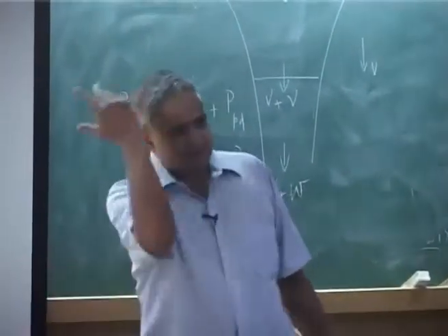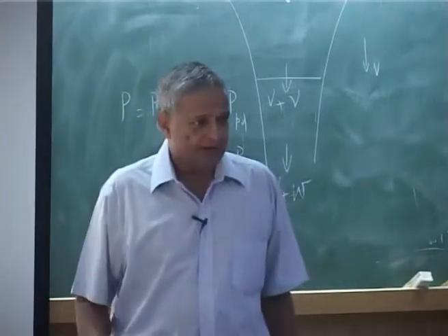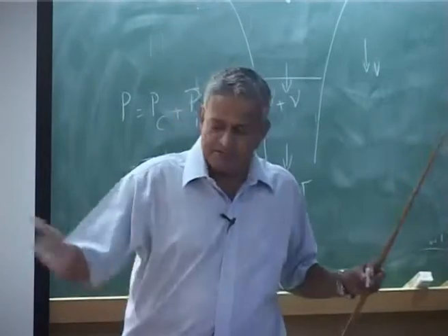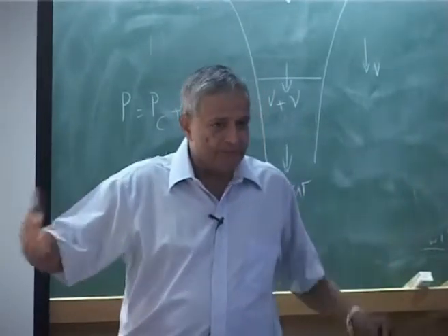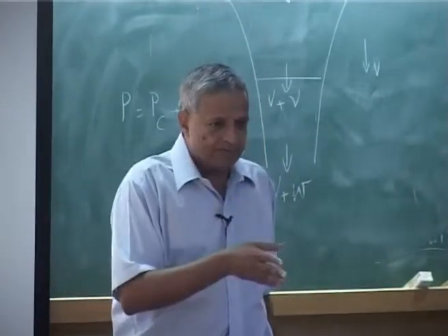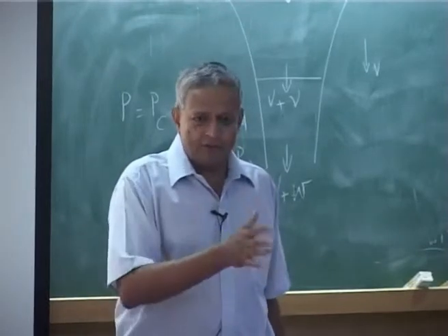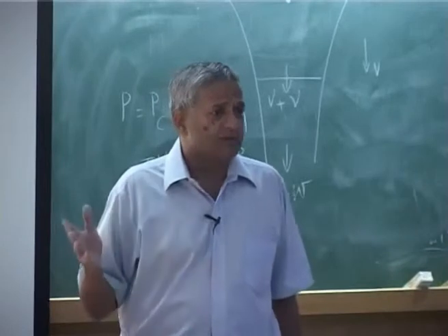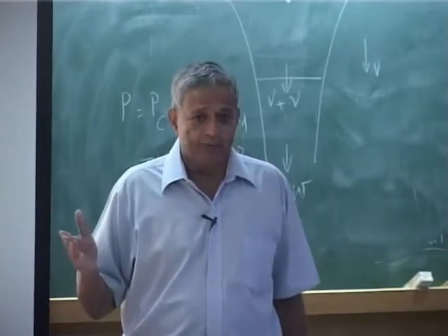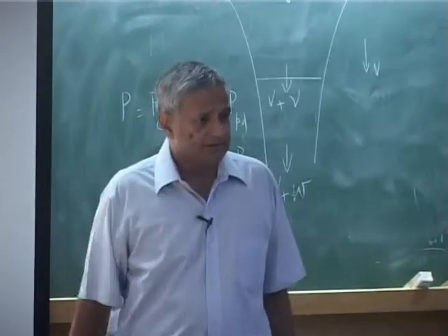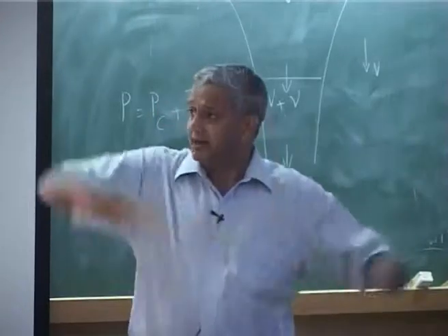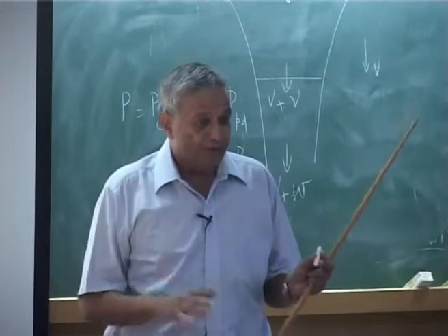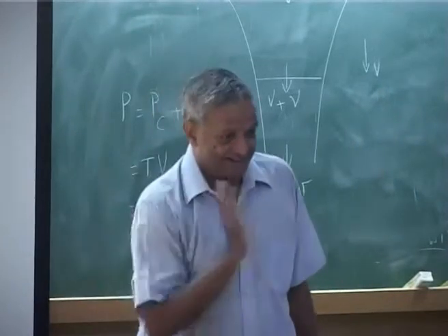Suppose you keep increasing your omega, what will happen? Your stress will go tremendously, because for most of the blades, for the operating omega, the root centrifugal force is of the order of 100,000 Newton. Now you double it, it will become 400,000 Newton, that is all, the whole blade will start flying all over the place. You understand? So you do not try to descend faster.